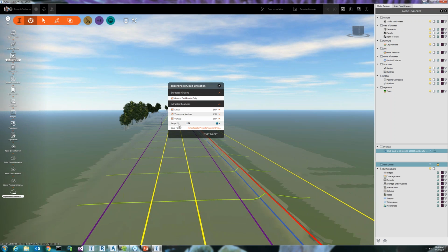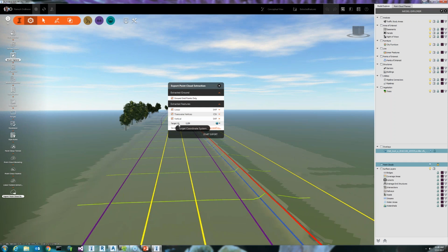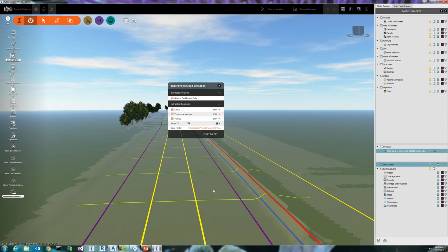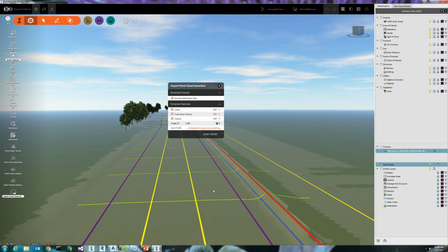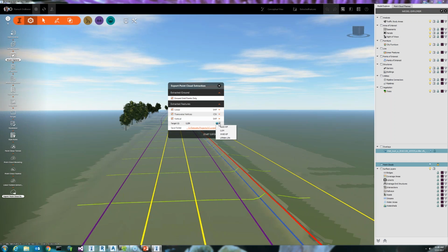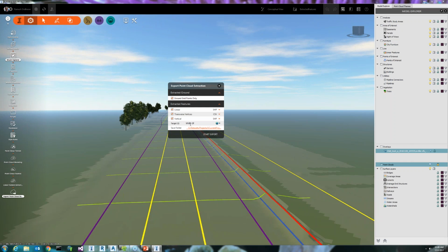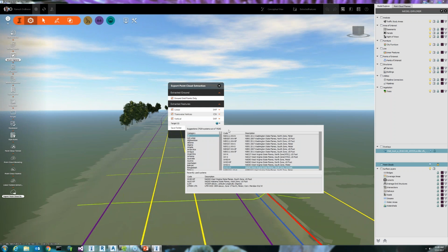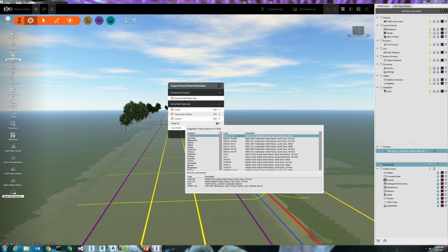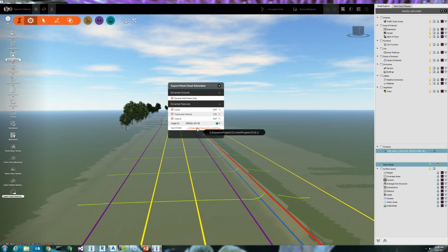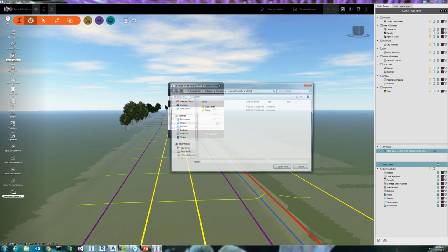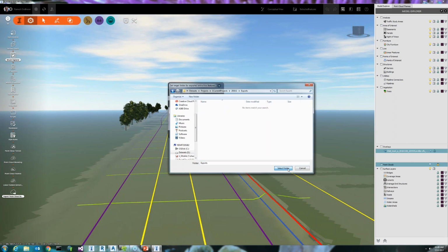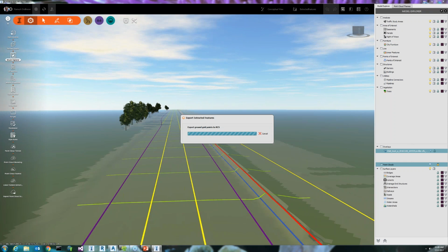And another beauty of this is you can specify the target coordinate system. You can work in any coordinate system in InfraWorks, but when you want to go into Civil 3D or any design, you obviously want the information you extract to match the drawing coordinate system. So you can specify whatever coordinate system you want. In this case, it's West Virginia, I think, but you can specify even more. You can just type in anything you want, and the software will reproject it for you and take it out in the area and specify the output folder. You get everything. I'm just going to show you exports and go.